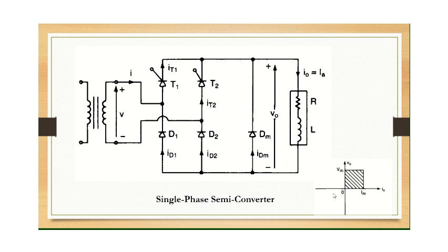So going to the circuit diagram, this is the single phase semi-converter. Observe the circuit there, which is highly inductive. In all the discussions in this chapter, it is assumed that the load is highly inductive, okay, and the load current will be continuous and will have a negligible ripple, okay. So assuming these basic assumptions, we'll go with understanding the working of the semi-converter. As you can see, the load is inductive. There is an RL load, and it is assumed that the load current is continuous.